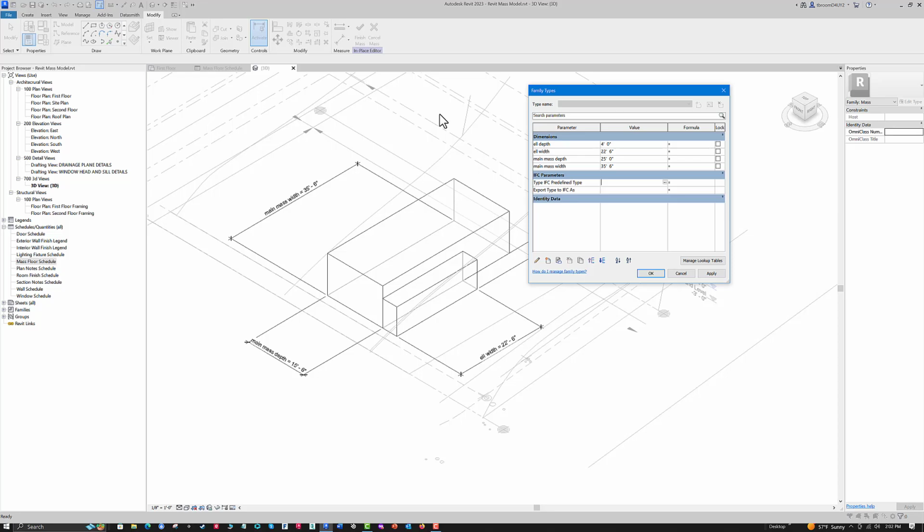And last consideration is the materials. Now, I said I'm doing frame. That's true, I am. However, this thing's going to sit on a brick base. And I want the brick base to look nice. It's going to be a design element. And since it's brick, what you want to do is you want to size it so that it can take the brick module. In other words, you can go ahead and lay this thing out with your brick and never have to worry about cutting a brick, because all the brick will either be a full brick length or a half brick length, and that works out fine.